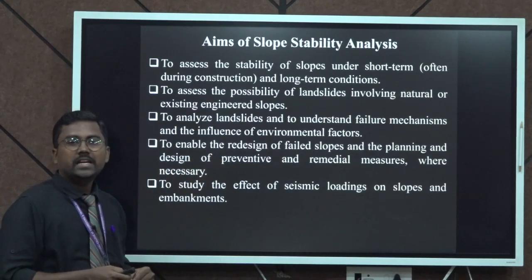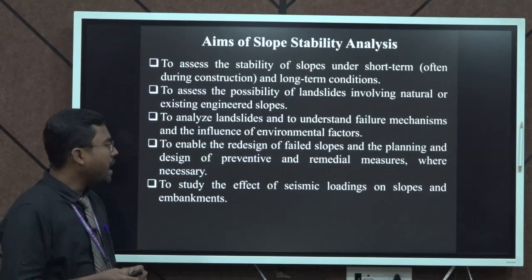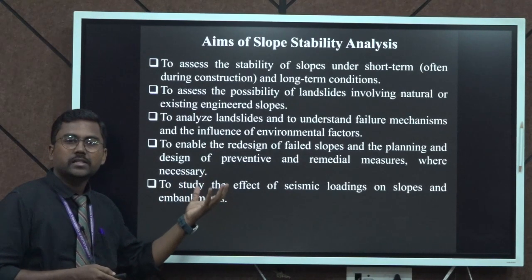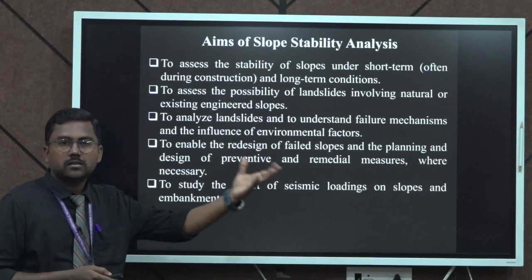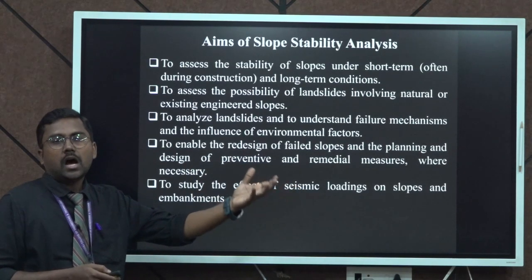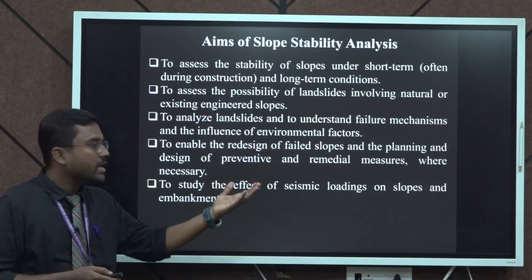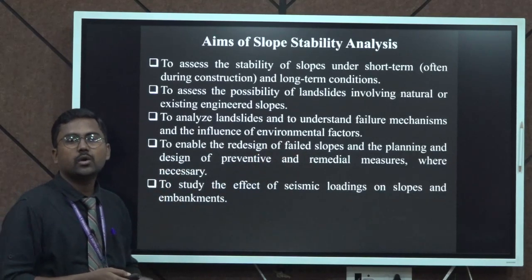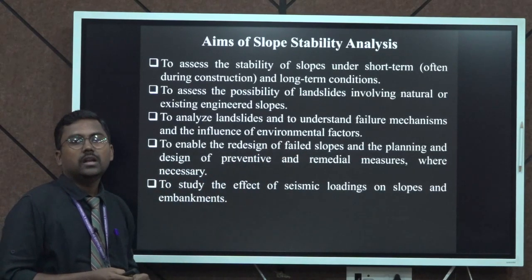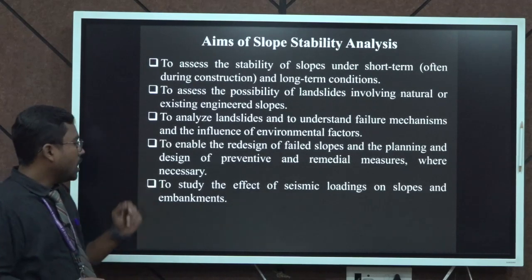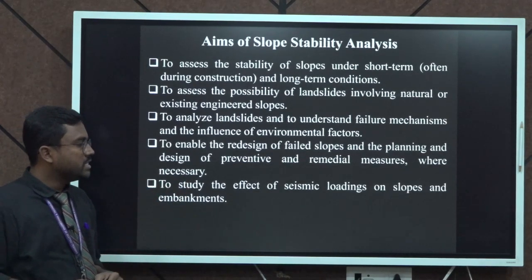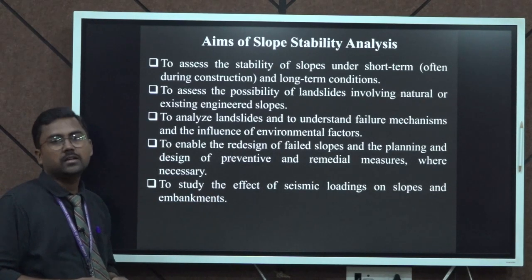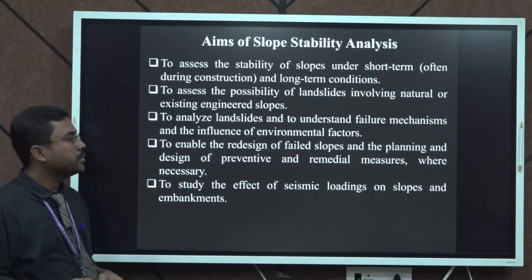And to enable the redesign of the finite slope and the planning and design of preventive measures. If a failure has happened, we can plan and design preventive and remedial measures so that failure will not happen on the slopes. And to study the effect of seismic load on slopes and embankments, how much earthquake force is acting, we can analyze by using the slope stability analysis.